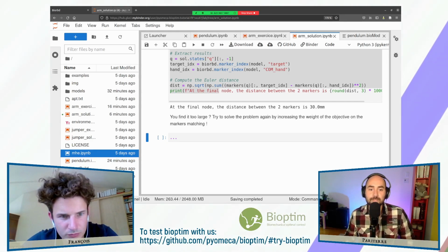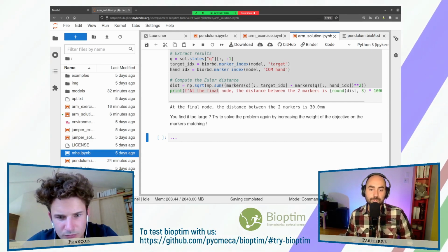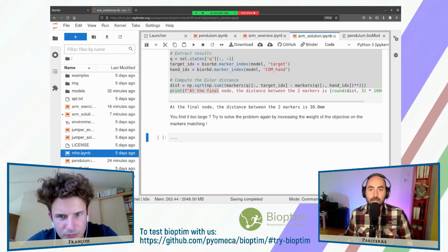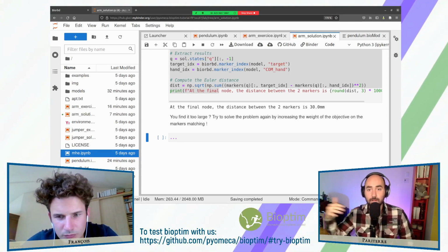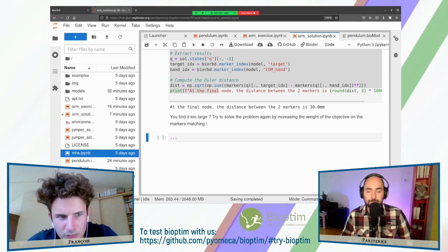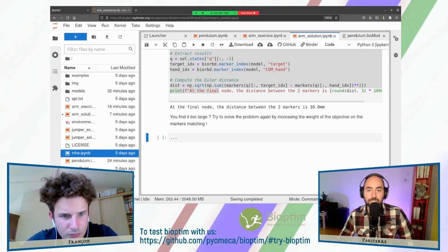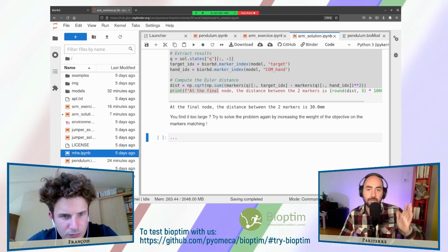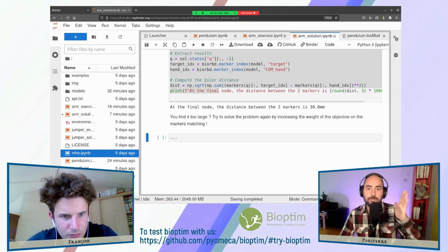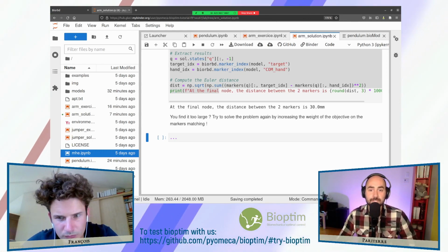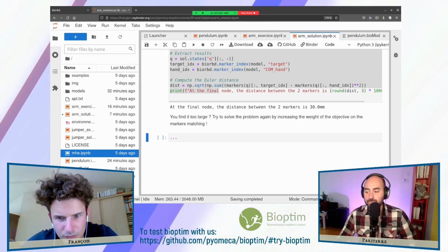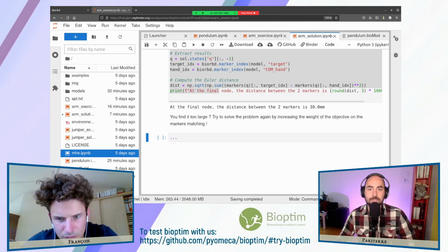And because the tolerances that we're using are so low, you can at the end take the control solution, take only the starting position of your system, apply some kind of single shooting simulation, and you should find the same thing as the optimal control program found.